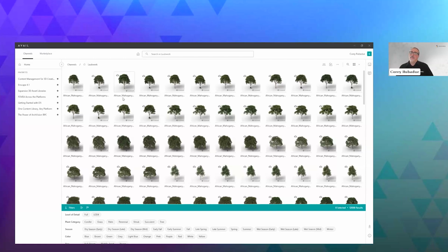Our file, which I'll show in a minute in Revit, doesn't necessarily show or depict the amount of density of the file that is actually rendered by your rendering engine. So in Revit, we have a proxy mesh or proxy object, which is much more lightweight. So we don't necessarily bog down Revit or your CAD application with the asset. I'm talking about a 2 million, 3 million triangle model actually bogging down a real-time engine when it's consumed in the renderer.